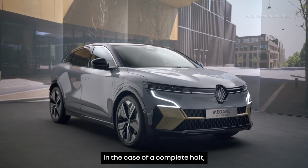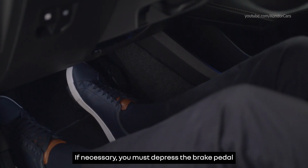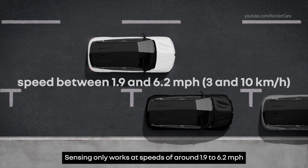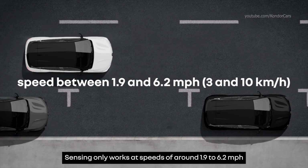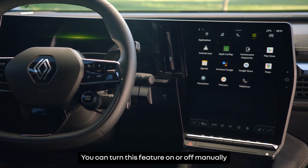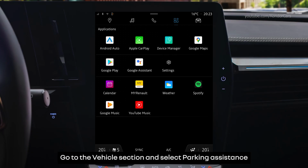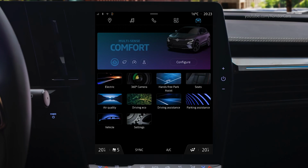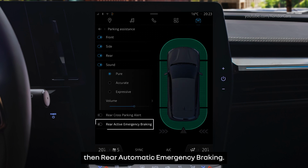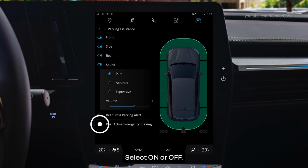In the case of a complete halt, the system ceases to apply the brakes. If necessary, you must depress the brake pedal to keep the vehicle stationary. Sensing only works at speeds of around 1.9 to 6.2 miles per hour or 3 to 10 kilometers per hour. You can turn this feature on or off manually from the OpenR Link center screen. Go to the Vehicle section and select Parking Assistance, then Rear Automatic Emergency Braking. Select On or Off.